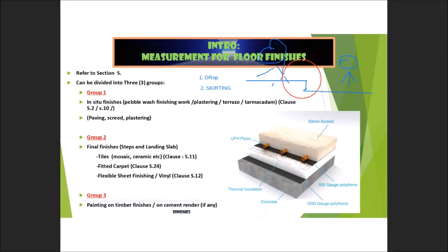Dividing strip is applicable when you have different material in one line. Okay, let's say this is the same level, okay, but I put another line here. So this is where you have divider. Why? Maybe because on your left you have cement render. Maybe on the right you have ceramic tiles. So you need to have the divider. Okay. So I group this one into the first category. At least you can see all this overview.